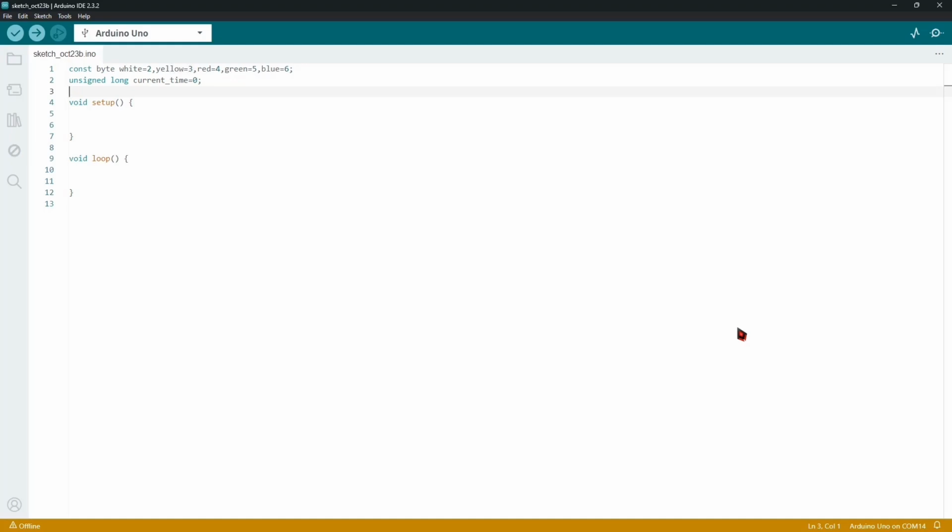Each LED has its own delay value, controlling how frequently it turns on and off. After powering the Arduino board, we need variables to store the specific timestamps in milliseconds when each LED turns on and off. These variables track the moments of state changes for each LED. Without them, it would be impossible to ensure that the millis function allows each LED to blink independently at its unique time intervals without interfering with one another.